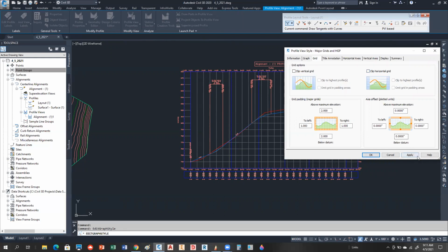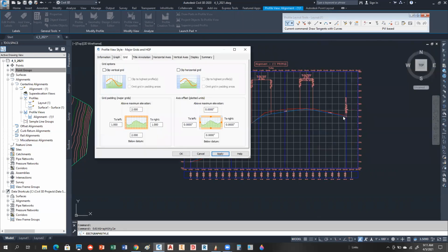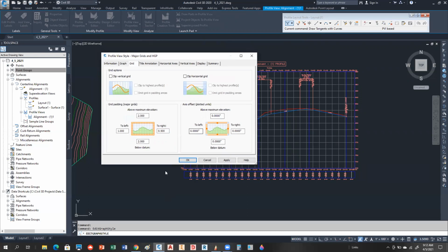One of the things you might want to do is notice at the end here, there's a lot of space there. If you don't want much space, top, bottom, left, right, you can clip some of that off. So for the right here, maybe I only want say a half inch. I'm going to go ahead and do that, and notice it brought that back. If you're trying to fit that in a viewport, sometimes that's really important. You guys getting that to work okay? Everybody?